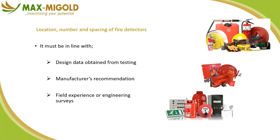When we have the layout of that building, then we can determine what we need to put in place. So the architectural drawing of the building will pass to the M&E guys who can then properly do a design to say we need this amount of smoke detectors here, based on the hazard in the room, based on the area coverage, and based even on the occupancy.